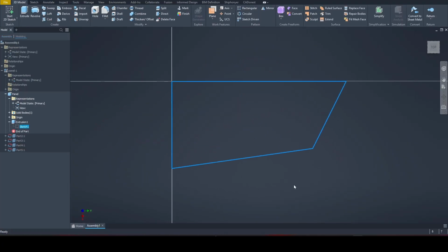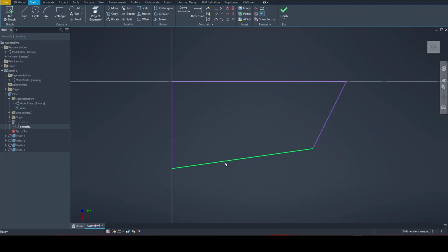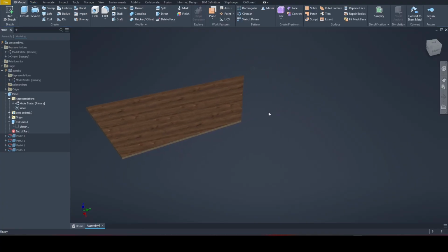The only thing you must not do is delete sketch entities and redraw them manually. If you delete a line and draw a new one, the edge bands will no longer be visible, and the command will fail, resulting in an error. Although the command is designed for rectangular profiles, you can always modify them to suit your needs.